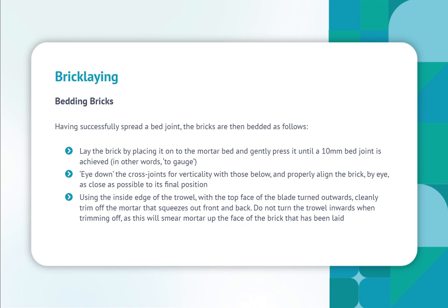Using the inside edge of the trowel, with the top face of the blade turned outwards, cleanly trim off the mortar that squeezes out front and back. Do not turn the trowel inwards when trimming off, as this will smear mortar up the face of the brick that has been laid.